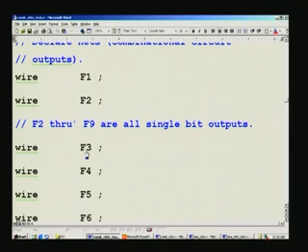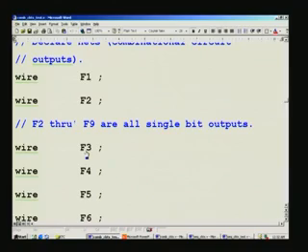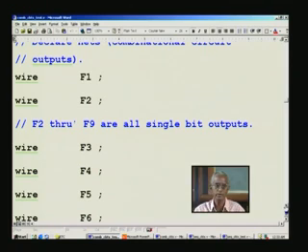You declare them as a wire, because it is a physical wire from one IC to another; its counterpart is analogous to that. So that is the reason why we declare it as a wire. This is applicable only in the case of the test bench. Do not confuse it with the design, where the declarations are entirely different. Based on the environment you are placed in, you have to see. So the logical reason is clear here.